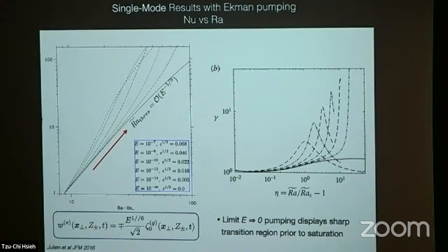In a sense, yes, you'll see that. If you look closely, you can see those signatures, even in the Nusselt number. You can actually see breaks in the Nusselt number, which would be like phase transitions, or first order phase transitions, where it's not gradual, something happens in the fluid. Certainly between the cells and convective columns, it's first order, yeah. The convective Taylor columns to plumes is probably a little softer when you look at the dynamics, I would think, okay.